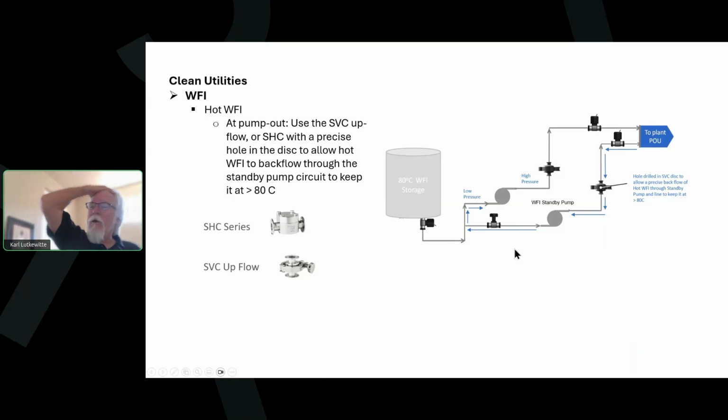We had some learning to do when we did this. The first disc that we did this with was either a PEEK or a Teflon disc, which we found, with the standby pump turned on, there was such a surge of force that it crushed the Teflon disc. So lesson learned. For this application, we always use our stainless disc with or without the EPDM seal. So keep that application in mind. It's a cool way to temperature validate the standby pump.